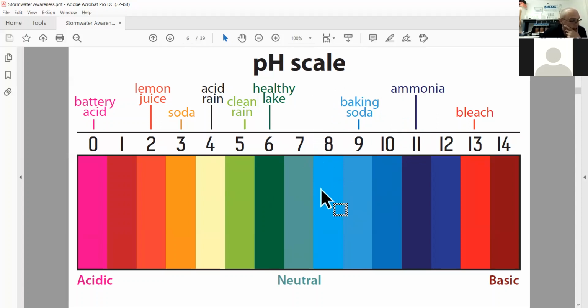To lower a high pH condition, an acid such as carbon dioxide or dry ice can be applied. Also, stronger chemicals such as muriatic acid or sulfuric acid could be used, but again, safety, handling, and application all have to be considered. In this case, dry ice or CO2 is a preferred chemical due to the safety factors and ease of application. And the same thing with sodium bicarbonate. CO2 has a hard time pushing the pH below 6.5. While it can do it, just like sodium bicarb can push the pH above 8.5, you have to really try hard to do that.